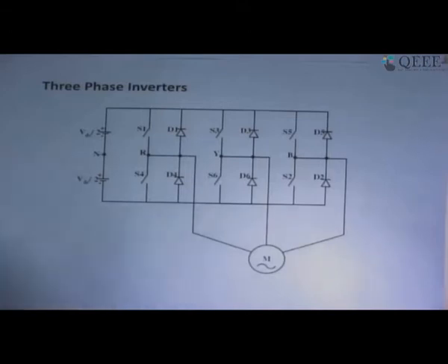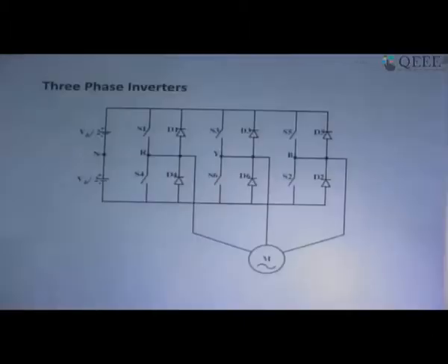Since the harmonics are at such a high frequency, they will hardly have any effect on the fundamental. We can neglect them if you are switching at anything more than 10 kilohertz for a 50 hertz AC waveform. So if we apply a sine PWM three-phase AC voltage to a three-phase induction motor, the currents are almost sinusoidal.